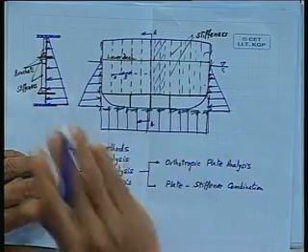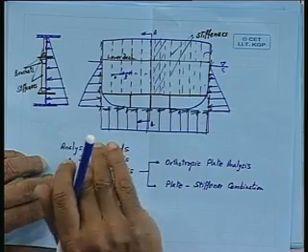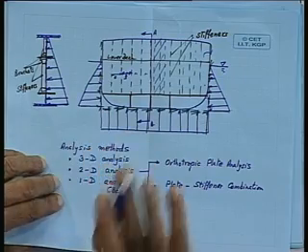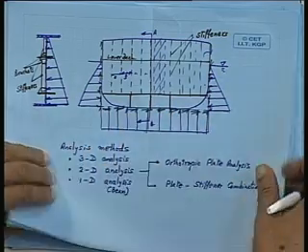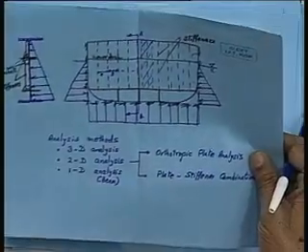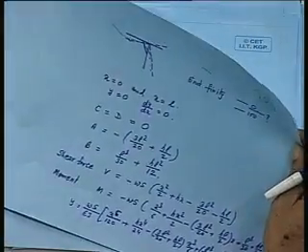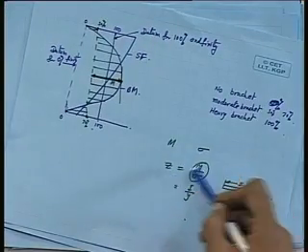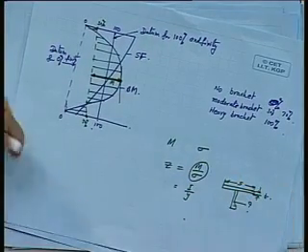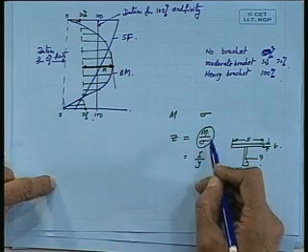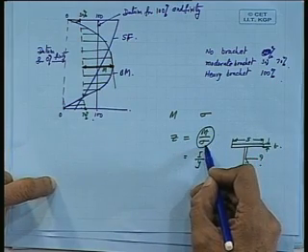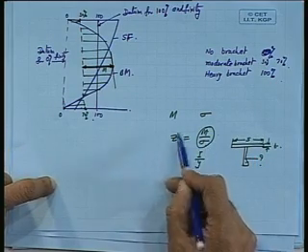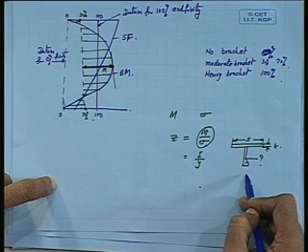So, based on that you construct the bending moment diagram, find out the maximum bending moment, and then based on the maximum bending moment we have calculated, this bending moment is known, the sigma is given to you. So, we know the section modulus of the plate stiffener combination.